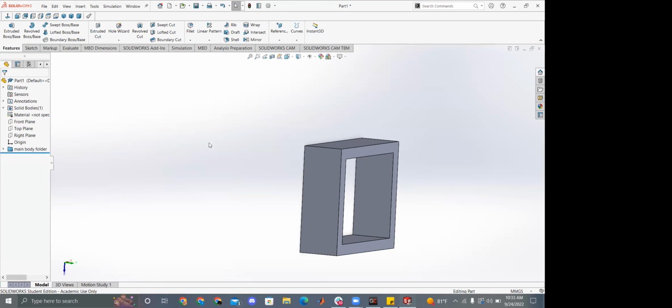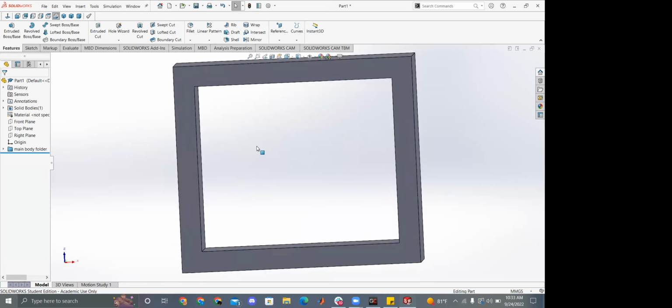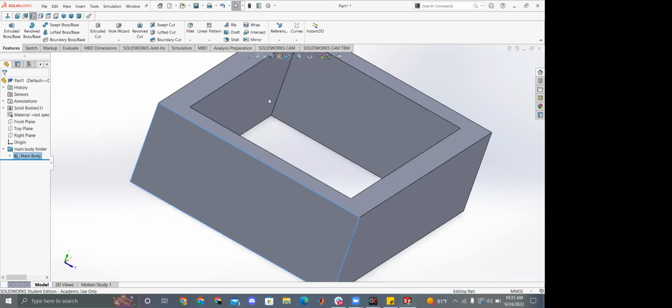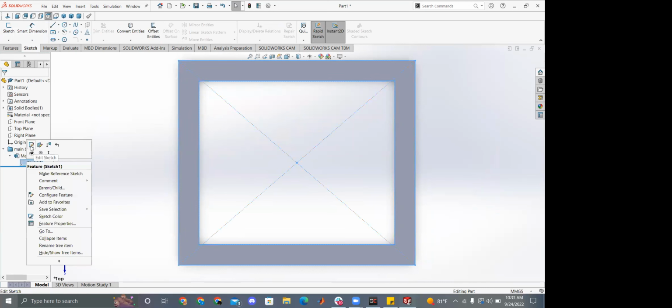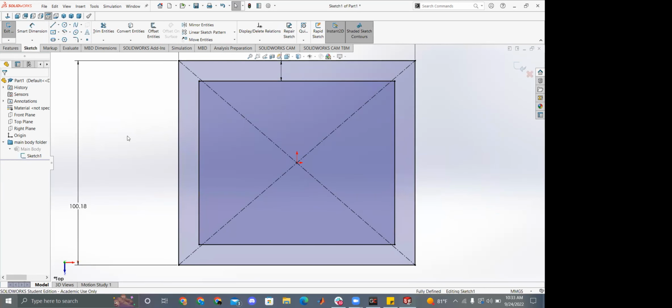Oh, something I didn't forget on my list, but is very useful. If you hold right click and you drag your mouse around, when you're not in the sketch, it'll snap you to a certain view. So it's pretty useful for getting into a view you want. When you're in a sketch, it will pull up some common features.